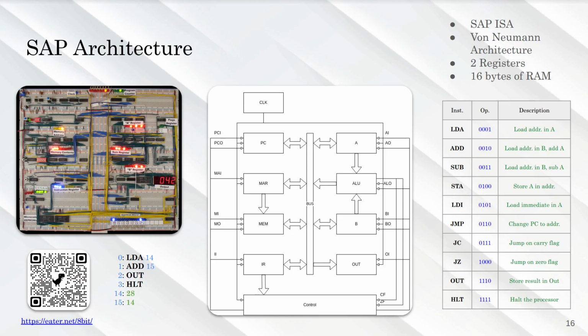This is referred to as the ABI, the Application Binary Interface, because programmers are going to encode the instructions using this Application Binary Interface, and the computer architects are going to build their CPUs with this contract between the programmer and the computer architects. That's great. So we have the load A, which, as I said, is going to load into the accumulator the value at the address that is part of the second nibble of the instruction.